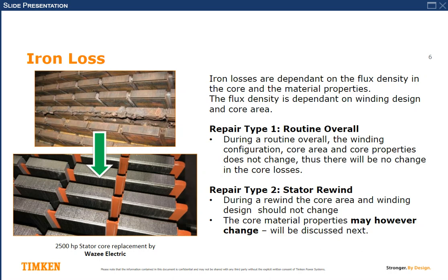also the core losses of that core were severely increased, and the core was found not to be suitable to be used. So the replacement motor will set back the customer with a delivery lead time of 6 months, perhaps even longer. So what we did at the electric workshop in Denver is we replaced the core with a brand new core that you can see at the bottom that restored the machine basically to new. The iron losses went down because it's a brand new core, and we had a machine that could work again.